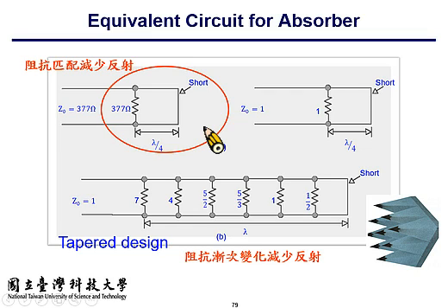So what is the combined resistance of 377 ohm with infinity, with open? The resulting resistance is 377. Okay, so with the Salisbury screen technique, you can achieve perfect matching.